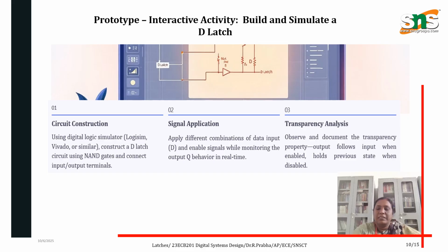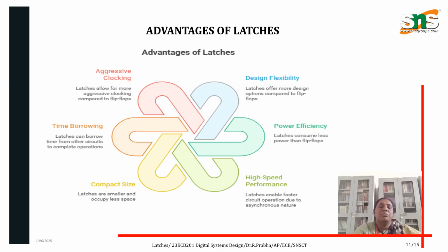So now advantages. There are so many advantages of latches. Design flexibility is very simple when compared to flip-flops, and power efficiency, it consumes less power, high speed performance because it is level triggered, and aggressive clocking it will allow. Time borrowing, so they can borrow time when other circuits complete operations, and size is very compact.